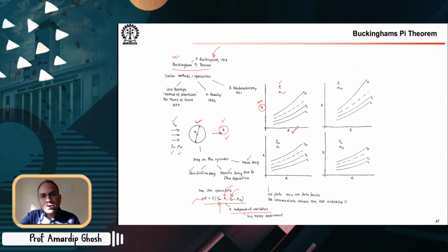So you measure the drag force on cylinders of various diameters. You hold the density and viscosity constant, in this case at rho1, mu1. You run the tunnels. For example, you might be putting this one in a wind tunnel. You are running the wind tunnel at 10 different velocities. And then for a given velocity, say v1, suppose you have 10 different diameters. So you are measuring the drag force on the cylinder. So essentially, you get 10 points for each of these velocity fields.